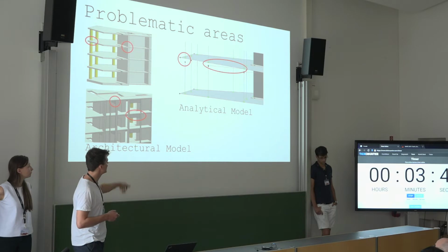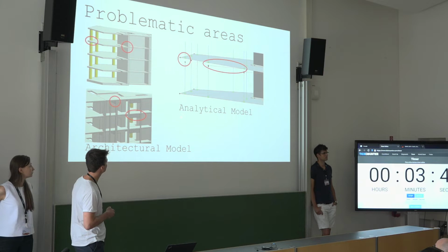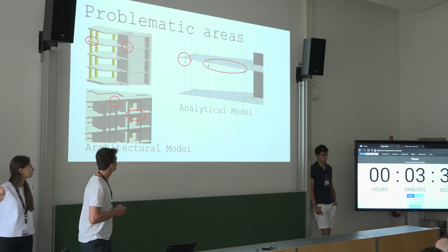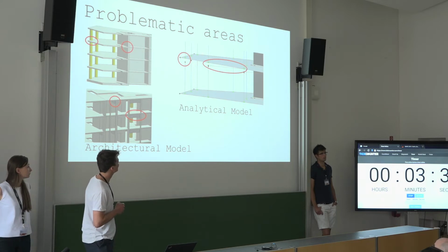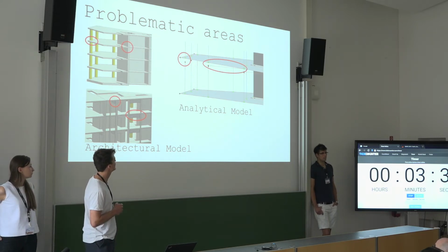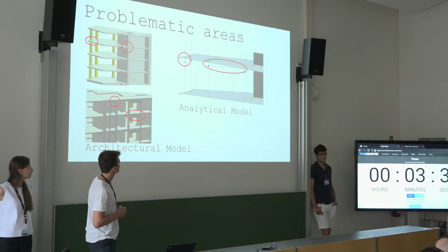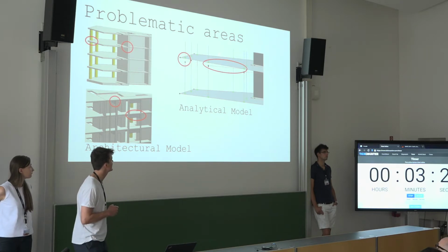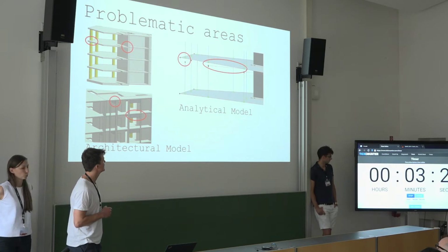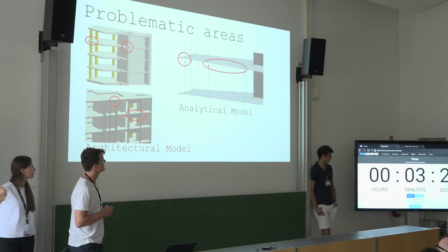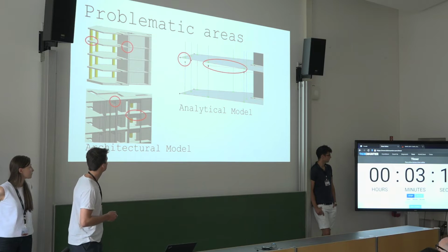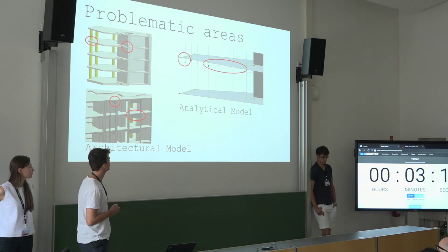And Revit is doing a great job on this already, extracting the analytical model out of the architectural model. But as we can see here, there are still some problems. It's still a bit buggy: the columns don't actually intersect with the surface, and the beams are not actually connected with the surface either. And we wanted to automate this process.